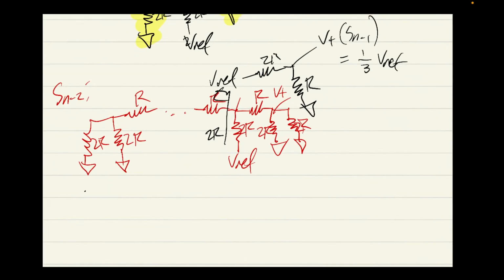So if we run that back, we end up with another simplified circuit, all right? And we can also simplify this right section, just for the sake of an initial analysis. Mind you, the right-hand side goes to ground entirely because this is a node going off to an op-amp. There's no current coming out of it, so we just consider voltage divisions.